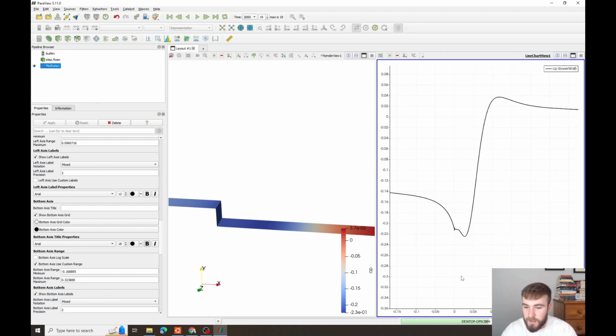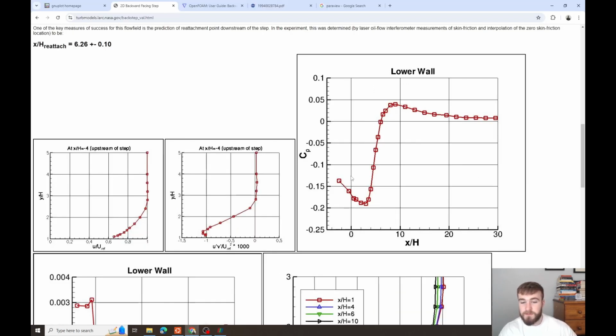And this pressure coefficient hits a lowest of about 0.23, then it rises up again, and then we hit a highest of about 0.36 or so. And you can see from the graph we have the same shape here, though not predicting it as exactly as this here, because obviously we probably have a different turbulence model and mesh and setup, etc. So it's about minus 0.18, 0.19 for NASA here, and 0.04 I would say there. So we're close enough, definitely in shape, and magnitude's a little bit off.